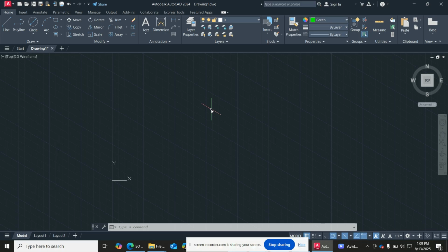Lakini kitu kingine cha msingi sana ukiwa unafanya isometric drawing, you have to activate the ortho mode, not the polar tracking. The ortho mode should be on so that it restricts your cursor to draw straight lines only, either vertical or horizontal, right? So let's see, tujaribu. Let's say tunataka kuchora box ambayo ni cube. A cube maanake ni box ambalo lina equal sides, right? Let's say we want to draw a box with 50 by 50 by 50, all three sides, right? Length, width, and height, right?